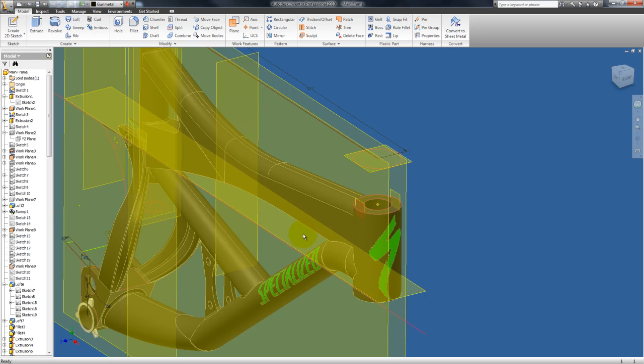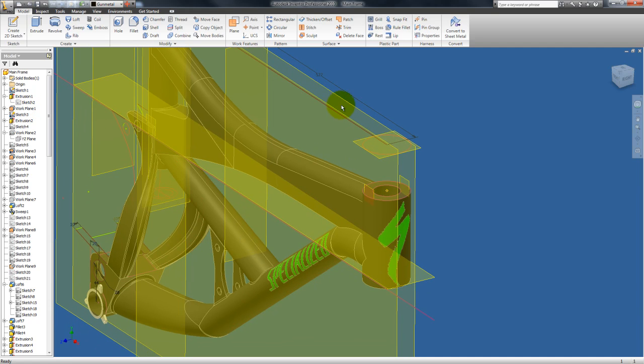So once you've created something, you can go back and modify it. Like if I want to be like, okay, this whole frame needs to be longer, I could just change some dimensions in the initial sketches that I've used, and everything will parametrically update. So that's the process. You just build everything off of initial parts. These are the fillets that failed. They were here. So I can go back and update those. I could just refillet them with a smaller radius. But anyways, you just build parametrically on top of previous buildings, and then everything will take shape, and it's very easy to go back and edit and change parameters.